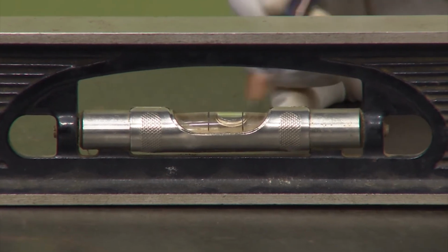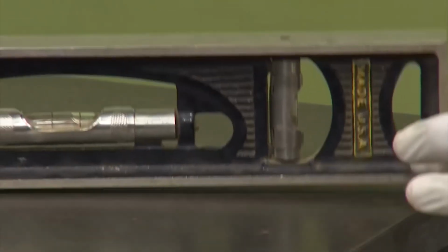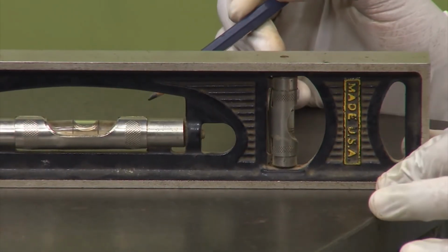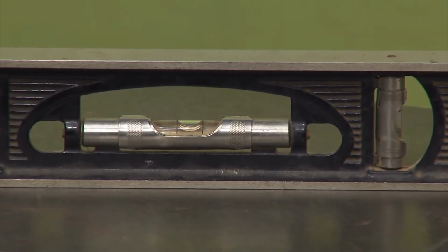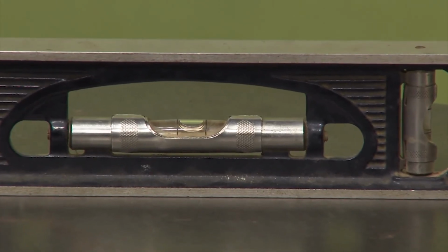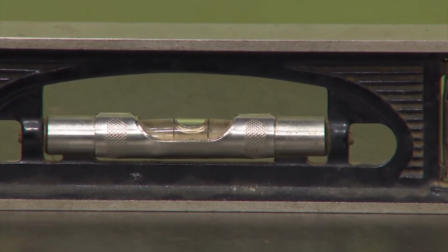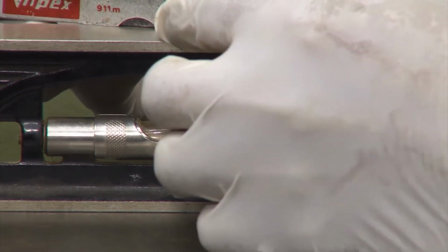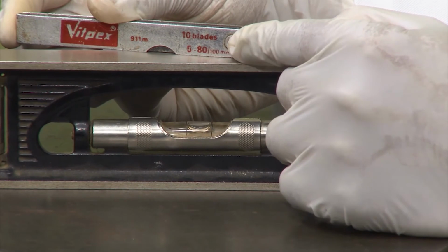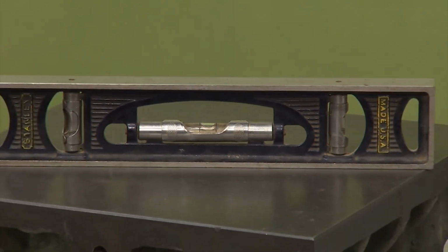That means this 4 mm is quite a large height to make it move. The sensitivity is the movement at which the bubble starts moving. If I make a very small movement like this, it is not moving, it is not crossing the marking. I can check it using the feeler gauge as well. This was the feeler gauge. We had various dimensions there, from 5 by 100 to 80 by 100. The finest leaf here is 5 by 100.